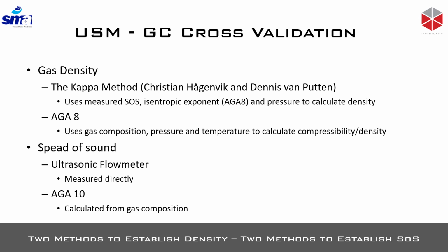The other thing that we can use is the speed of sound. The ultrasonic meter measures speed of sound directly, while the AGA-10 method calculates the speed of sound from the gas composition.